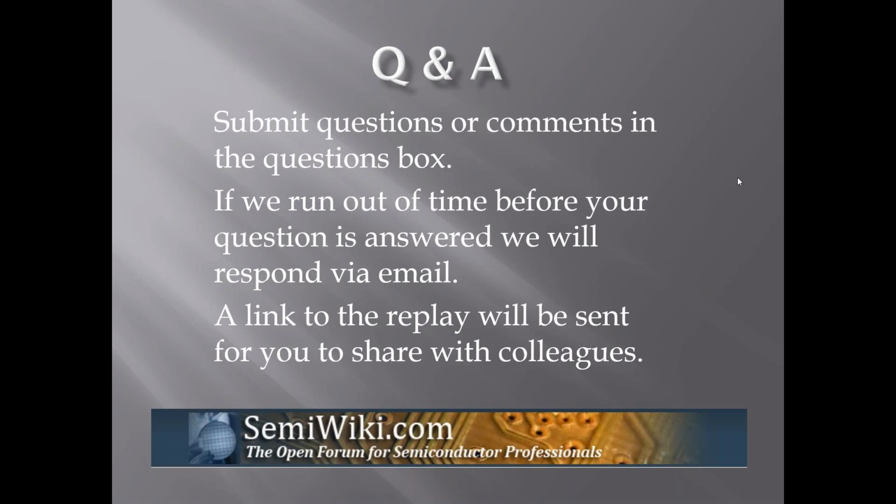They're not as well suited to block floating point because, as soon as you've done it in a GPU or CPU or even an ASIC, you've made a choice about what your number format will be, whereas that's difficult to do. Sometimes your mantissa will need to be a different size or your exponent will be a different size. And so that's where FPGAs in general really come into their own, in applications where you need a lot more flexibility.